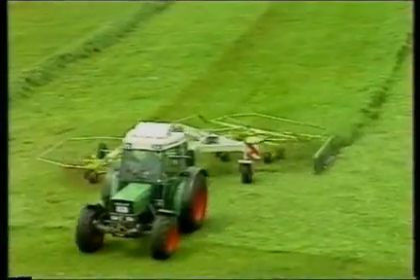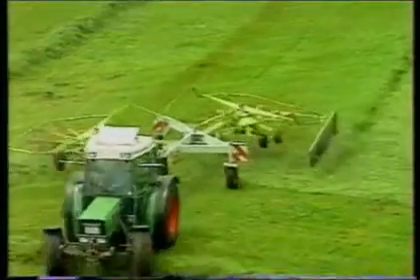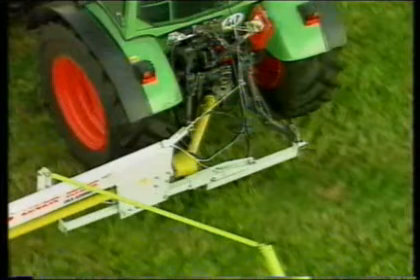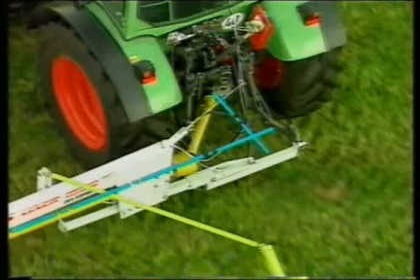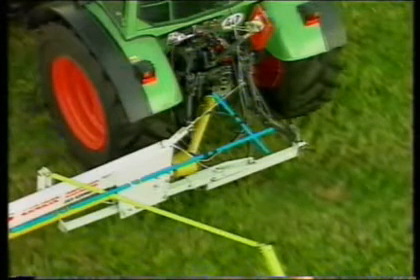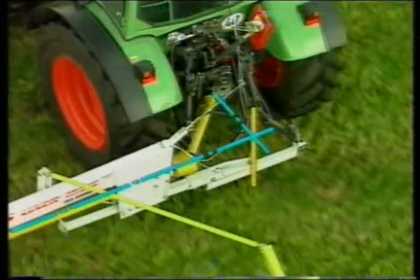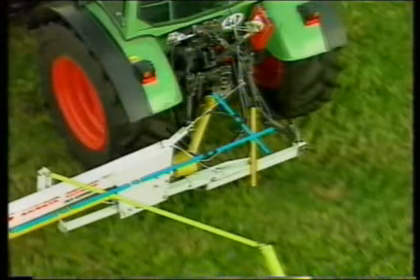The height must be matched due to the fact that a combination of W-bend and Z-bend leads to spatially uncompensated joint working angles. In the event of incorrectly matched implements, cornering without velocity variation is impossible, as shown by the calculation.